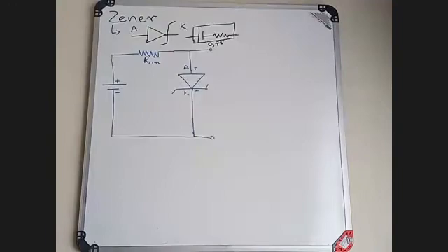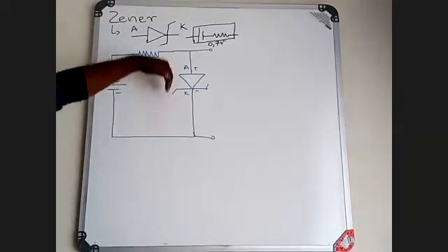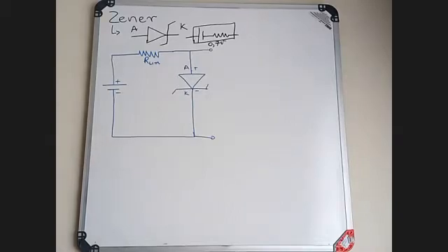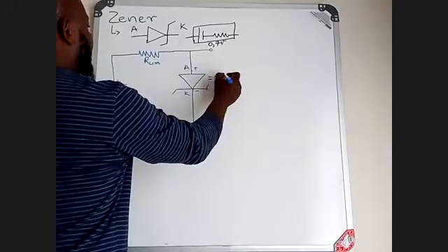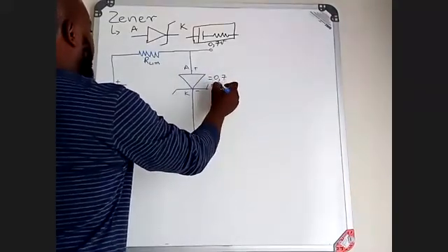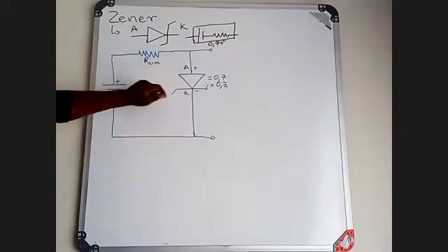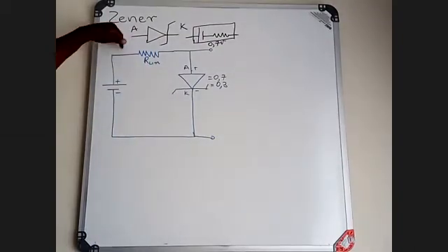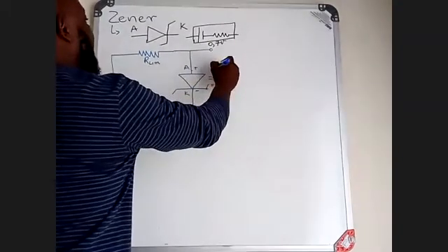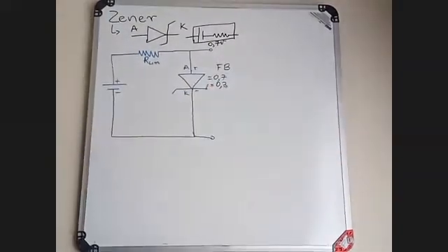I am going to measure the output of a diode. It is connected as a normal operating diode. Depending on what material is used, you will see that you get either 0.7 volt or 0.3 volt when it is connected in that manner. In terms of a Zener diode, this is taken as a forward bias mode.